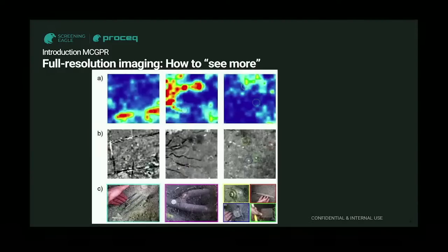And this is the resolution of what you can get from GPR. Along the top, we have 3 different versions of the same data set. The first one is looking at rebars. A is a single channel GPR, B is multi-channel, and then C is the actual image, so uncovering it. From single channel data where we can't see very much, as we move down, we can start making out exactly what it is that we're looking at, including these tree roots or these very small metallic objects.